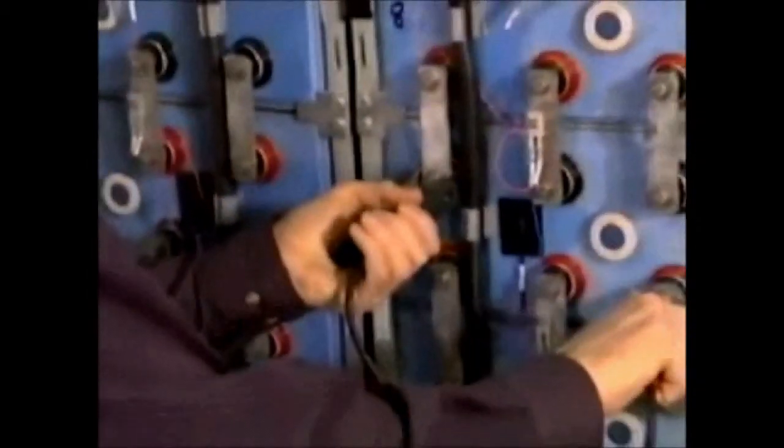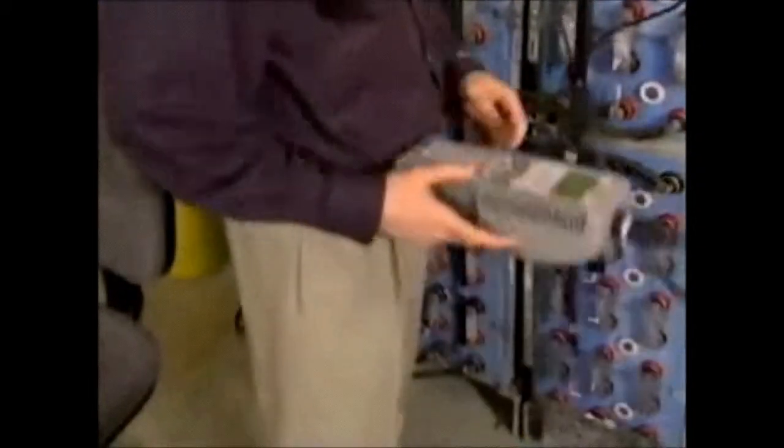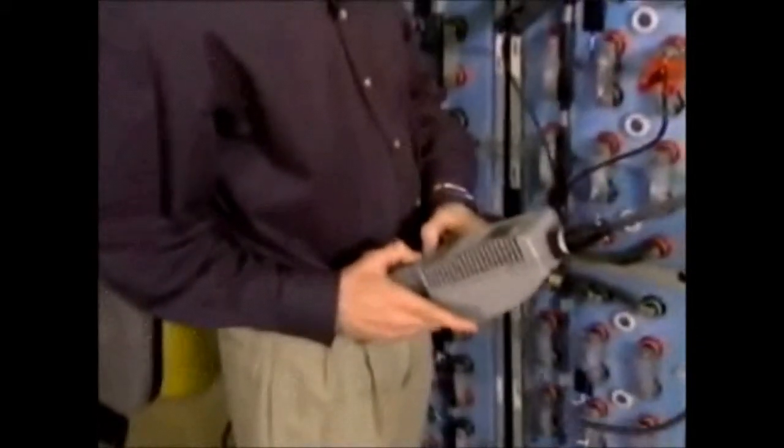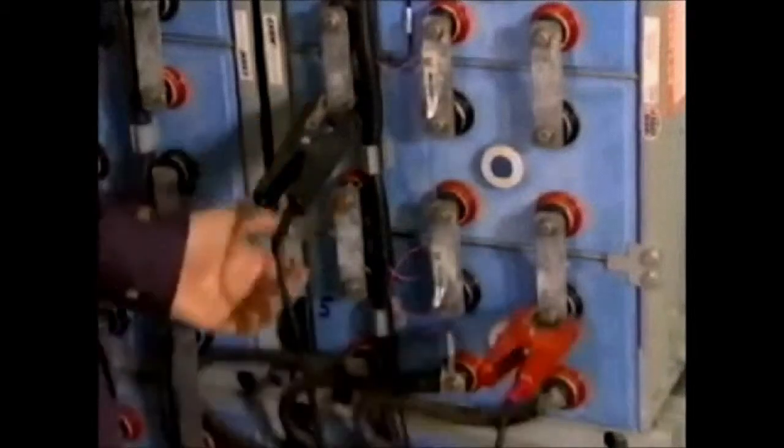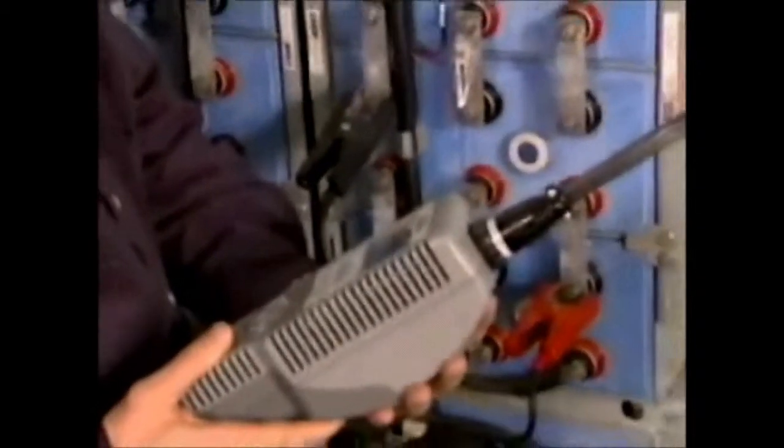On completion, we move one clamp to include both jar and strap, in this case jar 1 and the inner cell connection, or to jar 2. This measures the slight increase in resistance or loss in conductance through that strap. We continue on with jar 2. Test that jar, then again, including the strap.